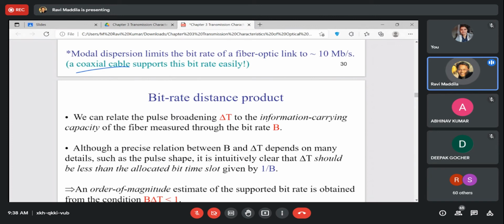If I consider 10 Mbps in a multimode optical fiber, this would be limited to about 1 or 2 kilometers. If I consider this over a coaxial cable, this also would be limited to about 1 or 2 kilometers. So the optical fiber as such does not have any major advantage. In that case, commercially, what is cheaper would be done. A coaxial cable is cheaper, so a coaxial cable would be laid instead of an optical fiber.